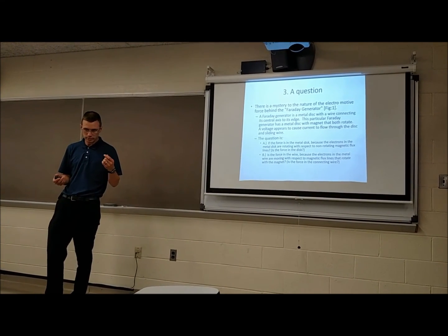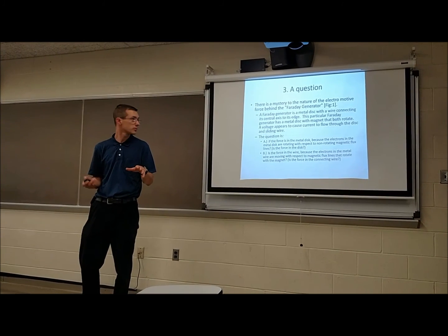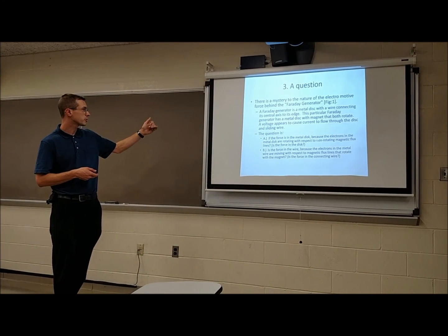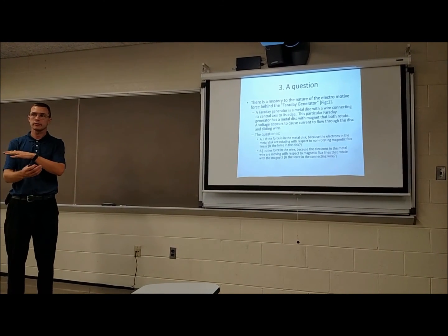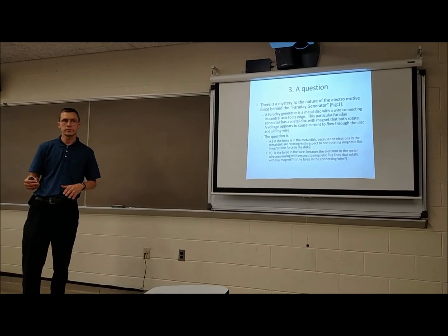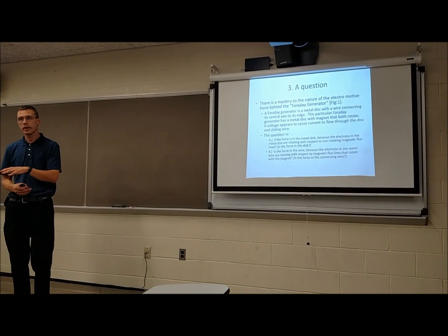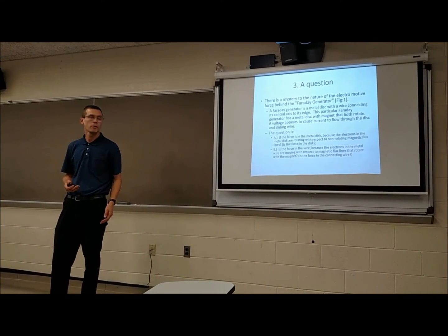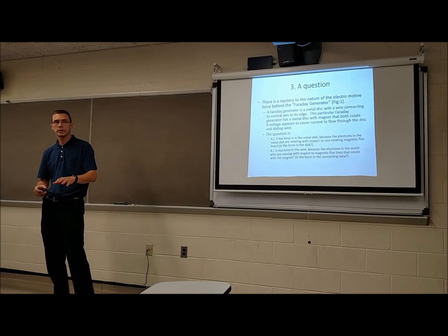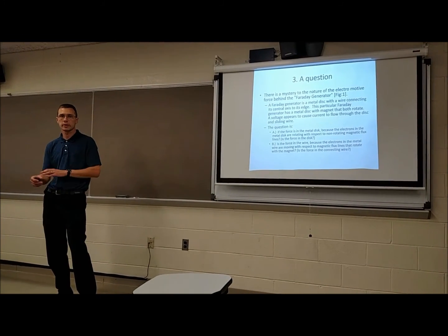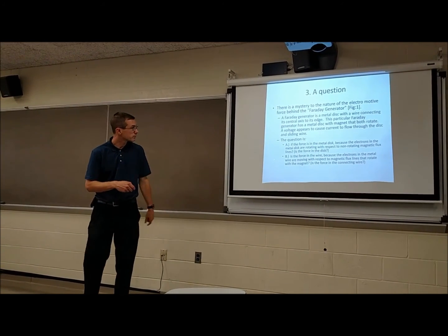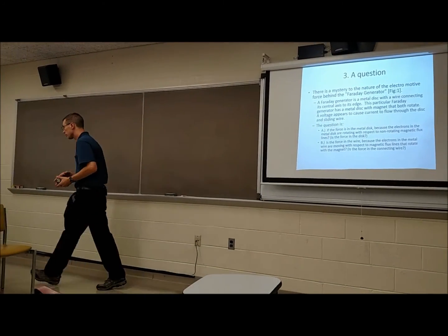So the question is whether or not the magnetic field rotates with this disk. And so the question I wrote down here is, is the force on the middle disk? So is the disk rotating through a non-rotating magnetic field? In which case then the disk is experiencing velocity through this magnetic field and it's experiencing an EMF. Or is the magnetic field rotating with the disk? In which case the disk is sitting still relative to a rotating magnetic field, and it's the connecting wire that's experiencing the EMF. So I'm going to show you a picture of this real quick.